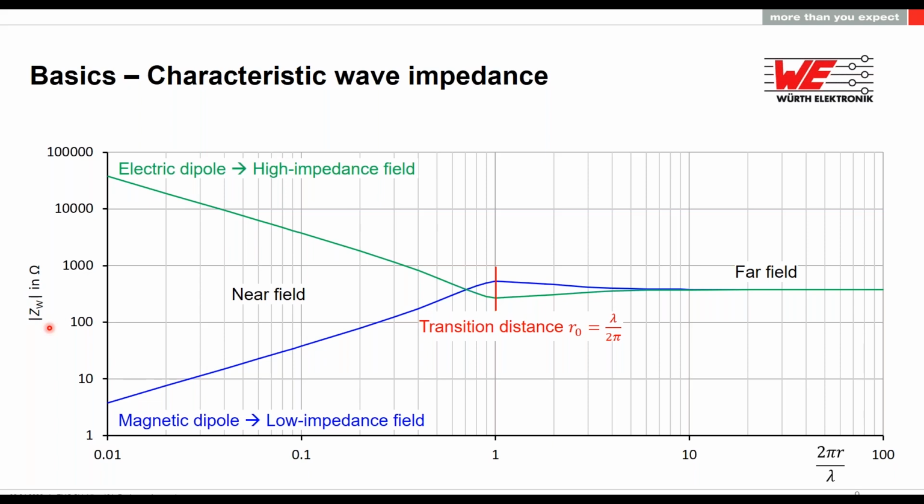You can think about it like when you design a PCB, you always want to have a common impedance. For example, the most common value is 50 ohms or 100 ohms. And you want everything on your device to be balanced and to have this impedance. So what happens if you have a trace and suddenly you place a really big impedance? The signal that is going through this trace is being reflected. The same happens when you are creating this mismatch for shielding.